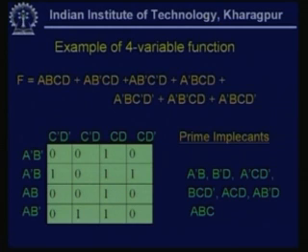Now, AB dash D, AB dash D, which is one? AB dash is the fourth row, and D is this one, that means here another couple can be formed, and another is ABC. So, ABC means this is my AB, and C means, so this one is the couple. Now, see, that means here for this particular example there are 2 quads and 5 couples exist.